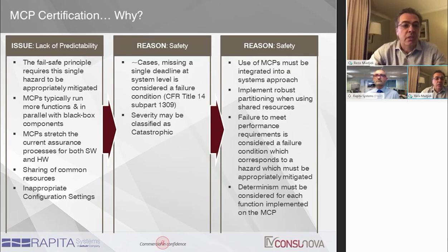The issue is the lack of predictability. The fail-safe principle that should prevent a single hazard or single fault from creating a catastrophic or hazardous situation has to still be intact. Multi-core processors have different types of what we call black box components, in terms of peripherals, that could create those types of interferences.